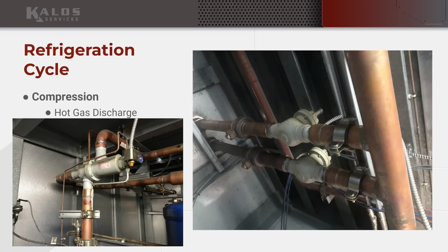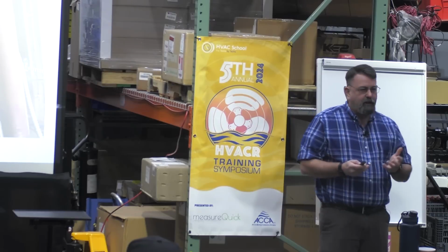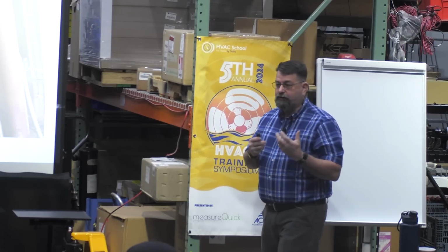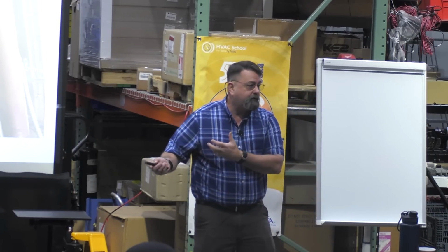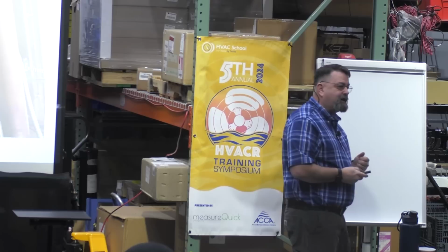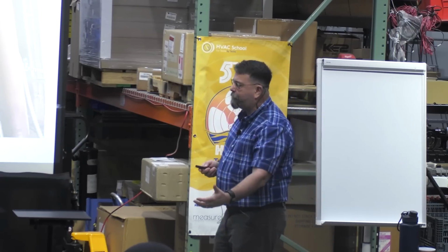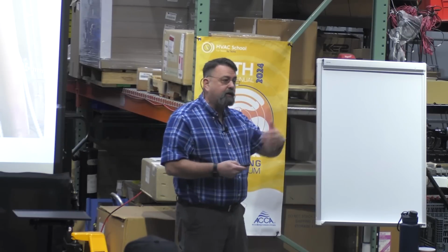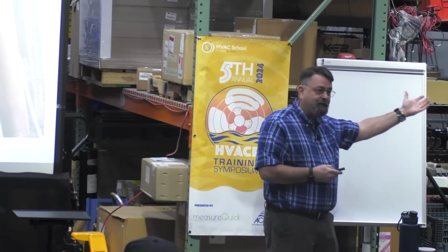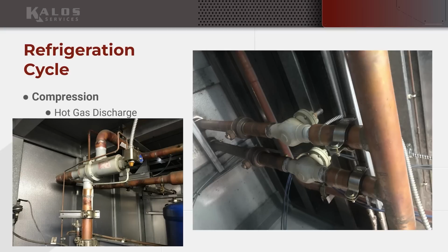When I move through the cycle after that, I've got a couple more things I'm going to throw in here. Now, these are actually fairly simple. We just need to know, all right? The first one is this three-way valve. What's going on here? Well, just like your reversing valve is allowing you to send your heat somewhere else, we're going to use that same idea. Because I'm creating heat that I have to reject to the atmosphere, that takes work to give away energy, right? I'm trying to get rid of it.